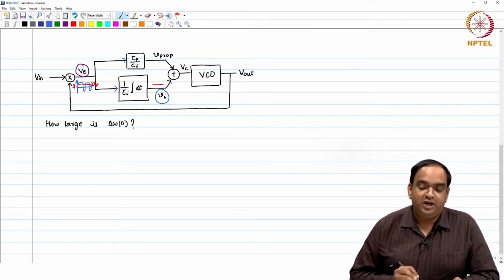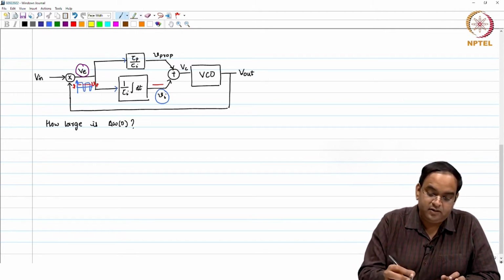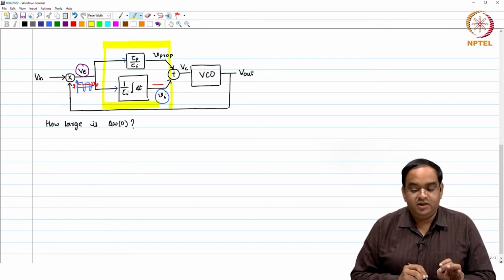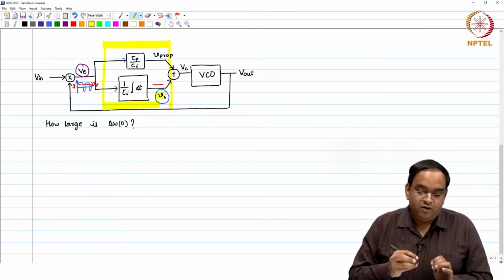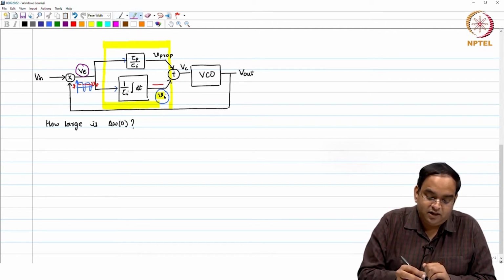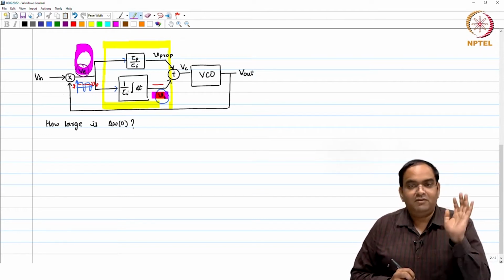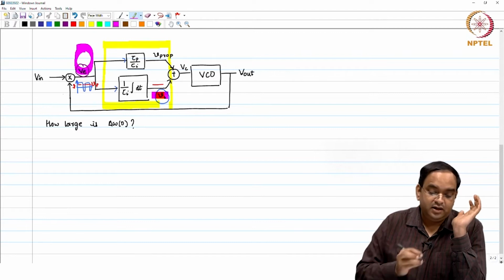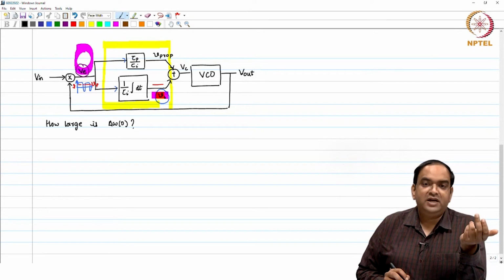So, it can generate any voltage, and in a steady state, this loop filter can have any voltage which you want at your output without having a non-zero input voltage. So, having a 0 here and a non-zero Vi, whatever value you need, that is practical, you can always get it. If that is the case, then it does not matter what my initial frequency error is.